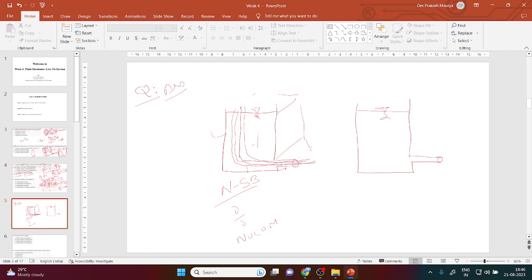Okay, so now the point here is that a lot of streamlines are flowing out from that location, so the Bernoulli equation is applied along only one streamline. You just apply your Bernoulli equation at that location. At both locations the pressure is atmospheric.